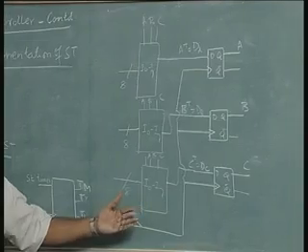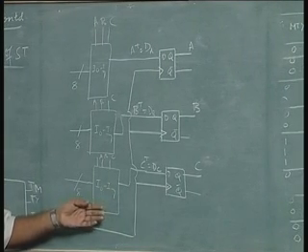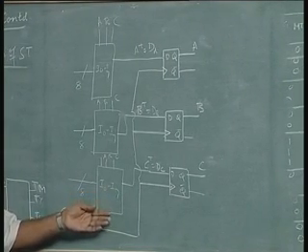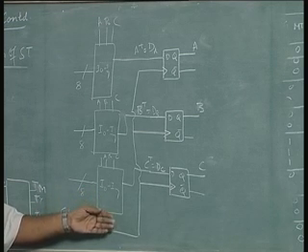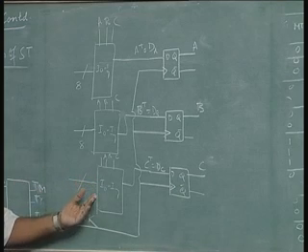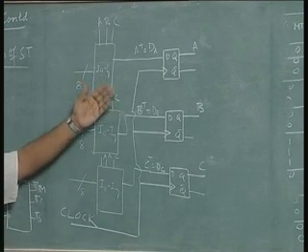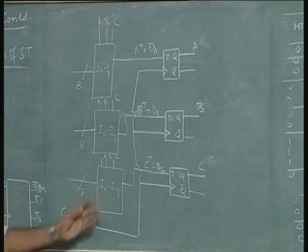This architecture is common. I do not want to be doing this repeatedly, because somebody asked here in this class. I again did this because we have done it several times before. We did it in the case of state graph, we did it in the case of the first example in the multiplexer, to avoid repetition, and also because by now you are familiar with this architecture. Output of the multiplexer drives the flip flops, that is it. You have to assume all this. This architecture is standard.